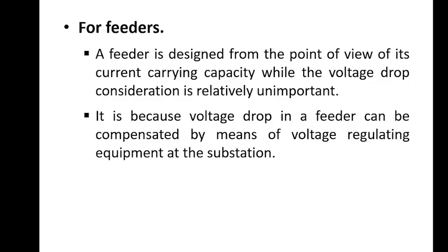Okay, this slide focuses on the design consideration for feeders in the distribution systems. A feeder is primarily designed based on its current carrying capability, meaning it must be capable of safely carrying the maximum expected load current without overheating or causing damage to the conductors. In this case, voltage drop along the feeder is considered less critical compared to its thermal capacity.